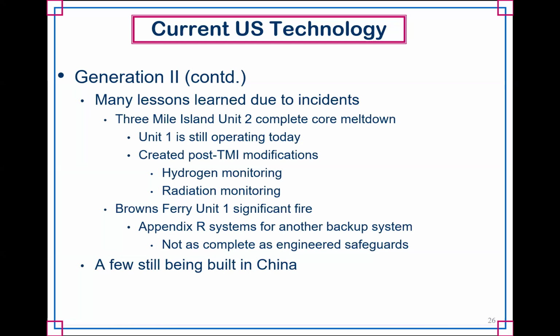The difficulty, though, was when they had designed these systems, they hadn't considered that there might be elevated levels of hydrogen inside the reactor, because when you heat up water to certain levels, it's possible that you can separate the hydrogen and the oxygen molecules, and then you can have buildup of hydrogen, which means you could have an explosion. You could have an explosion with just vibration. It's that unstable, at certain concentrations. You also had very, very high levels of radiation that they couldn't monitor with the equipment they were using because it was unexpectedly high. They didn't anticipate that.